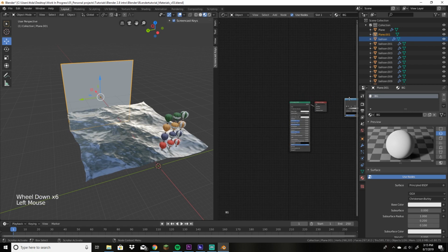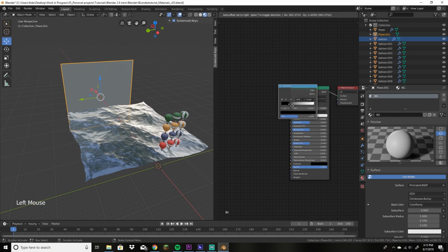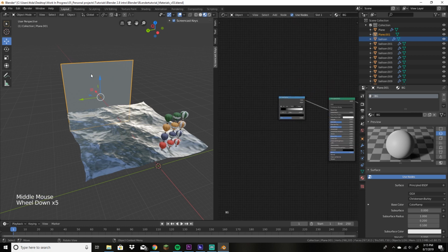Where did my color ramp go? There we are. So, if we connect that in, unfortunately, it doesn't put a gradient on it. It just chooses the middle color. If we want to actually put the gradient on it, we have to use some trickery. So first things first, if we're going to put any type of image, and I guess it would consider this an image of sorts, onto the face of an object, you need to UV unwrap it, which becomes a complicated process for this little guy here.